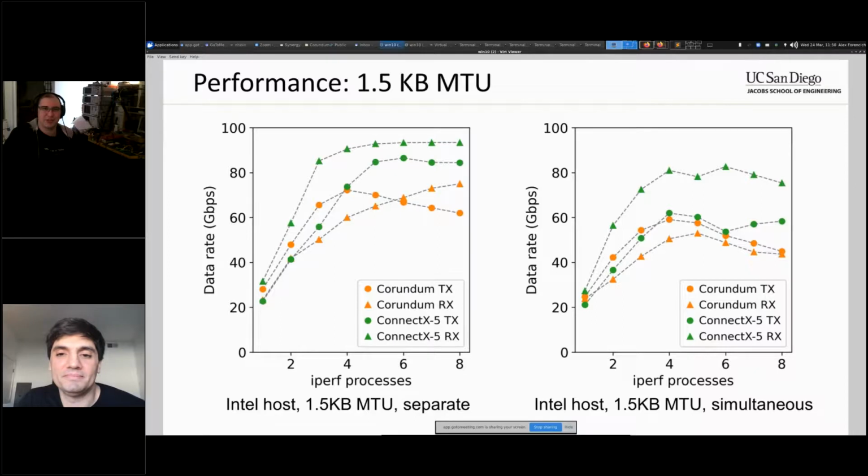So the hardware clock, I don't think there's much to do there, but the clock domain it's running in is the PCI Express clock domain. The reason we did that is so we can have direct register access to that clock. But that's not necessarily the best solution. It might make sense to run that in a different clock domain that's going to be more stable than whatever the host is providing. I think that'll affect probably the holdover time and who knows what else. But for our applications, we're trying to do microsecond precision TDMA. So as long as we can time sync within a microsecond, we're good. We don't need to do any better than that. For other applications, you would need to do better than that.